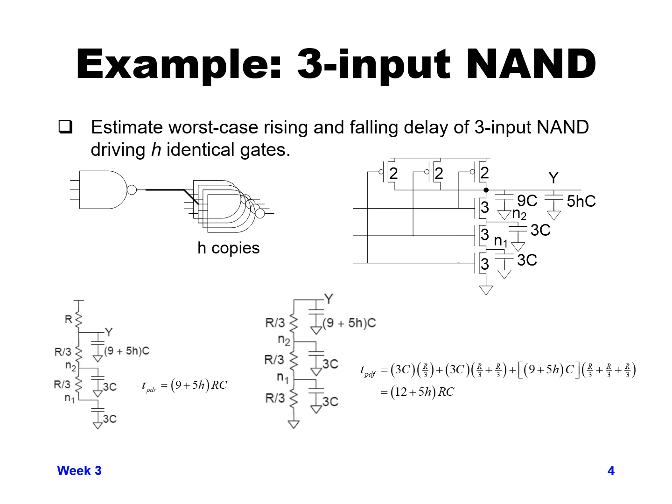Now going through the second part of the resistive ladder, we have another 3C that's now being driven by 2 resistors in series with each other. Each is R over 3, so we have R over 3 plus R over 3 driving the second value of 3C. And then finally, driving the output node, we have 3 resistances of R over 3 in series with each other.